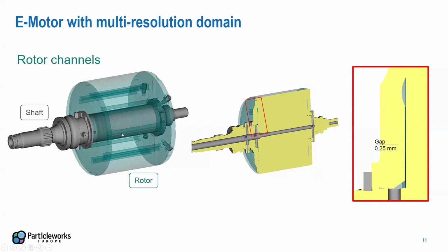So we see increasingly oil cooling in e-motors, because this strategy with jets coming also from the shaft showed better cooling efficiency as compared to a water jacket around the stator. But one tricky part could be small gaps in the rotor channel, distributing channel, like you see here.